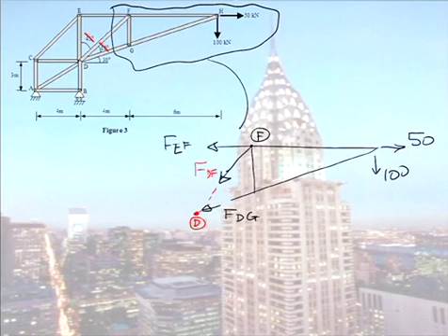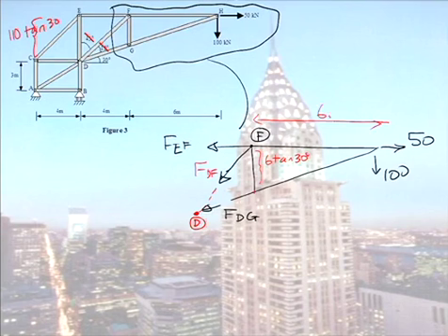So I can use that potentially as a point about which I'll take moments. Now, as we calculated this length here to be 10 tan 30, this length in here, if we need to know it, is 6 tan 30, because that distance in there is 6 metres.